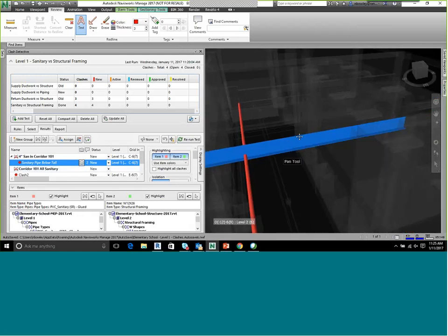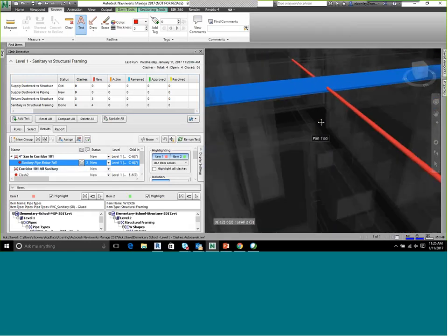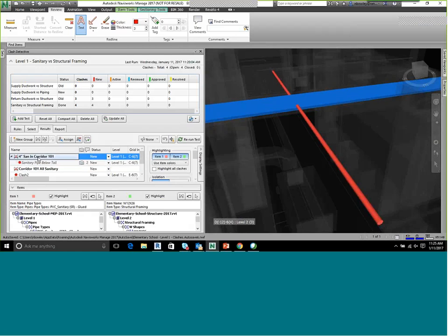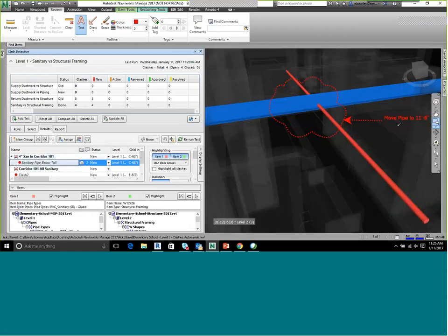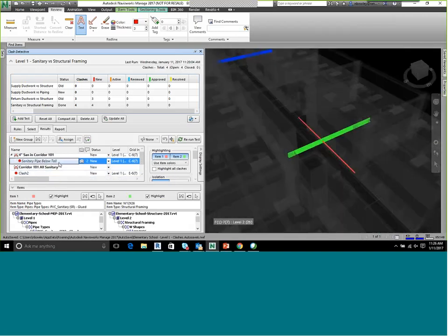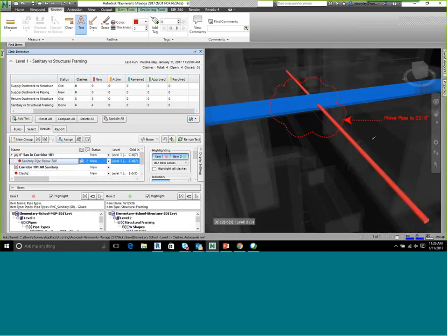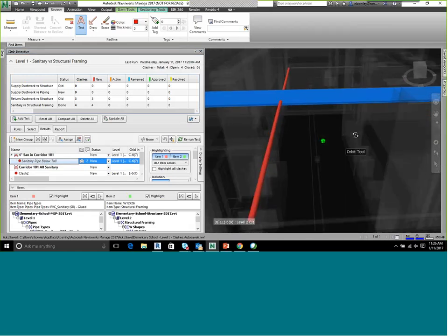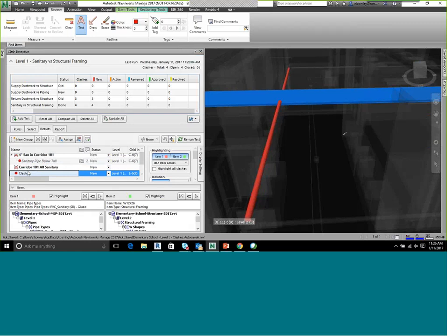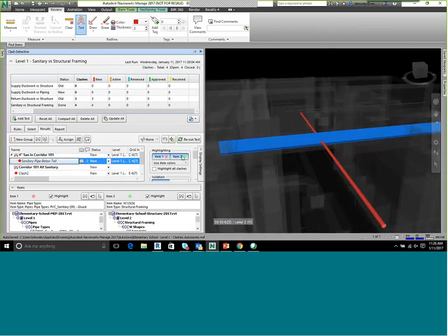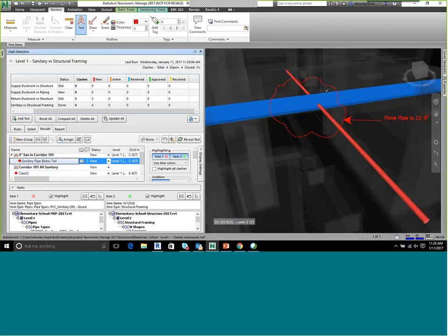All right, so I just panned, and you'll notice that my comment disappeared. That's okay, because when I come back to it, the comment's still there. I didn't really update the view, but I just wanted to show you as you're navigating, the comment is still there. Again, for a non-Revit user, it might be confusing that your comments disappear once you change your viewpoint. So these are viewpoints, and the text only exists in this viewpoint. Once you start moving your camera, you're no longer in that viewpoint, which is why your comments disappear. Make sure you like your viewpoint before you save it.